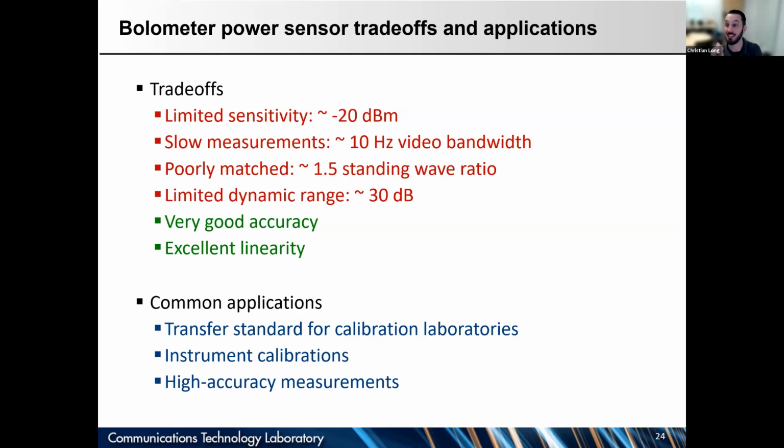So the DC power measurements tie to voltmeters and current meters or resistance meters, and DC measurements of resistance and voltage have more decimals of accuracy and precision than I dream of in microwave measurements. So it's very nice that this kind of power sensor inherits the linearity of DC metering electronics. That can make it very nice as a metrology tool for microwave connections.